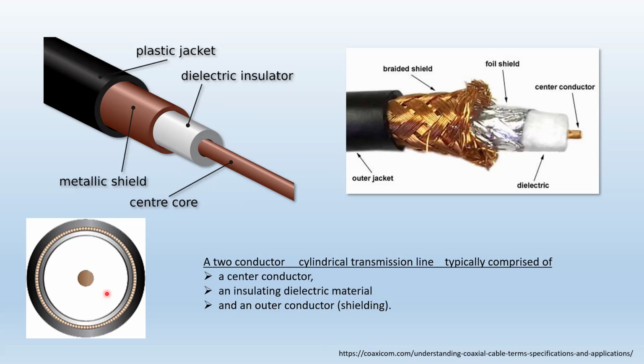On the outskirts, when you're leaving London, on the left side, you're going to see those huge long wave antennas for the AM transmission. Those antennas are provided with the signal by a coaxial cable, but it's a huge cable. In that case, with that size of cable and that length, the dielectric that separates the inner conductor from the outer shield is basically air. And there are so-called standoff insulators placed along the cable to keep it in the center.